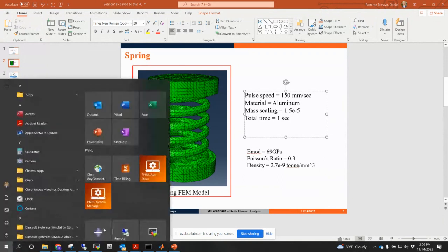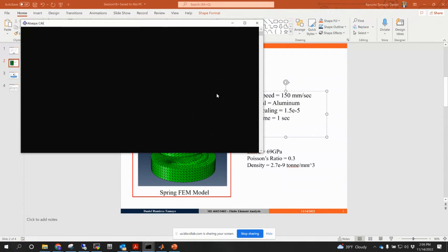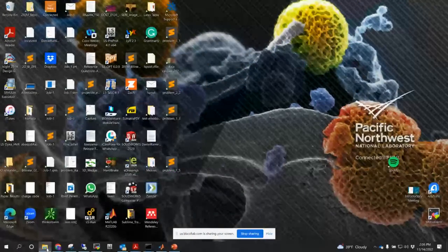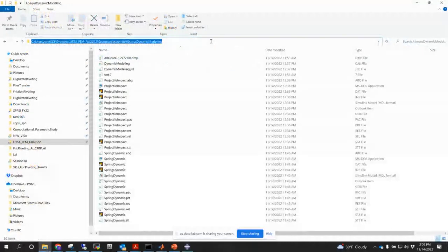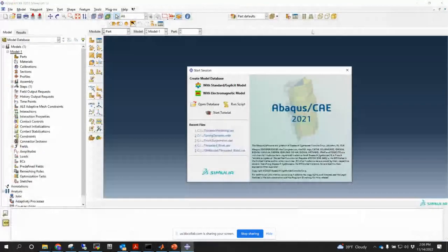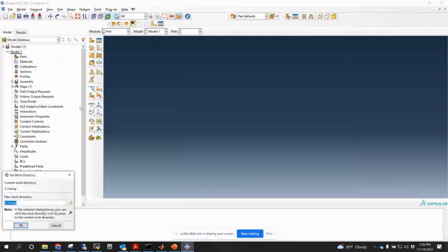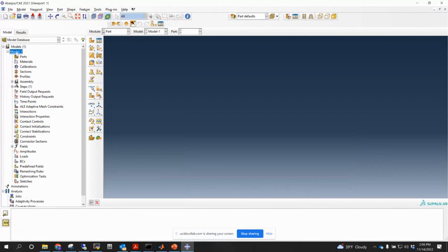So let's open Abaqus. And I'm gonna work on this working directory that I have in here, all right? So I'm gonna file, set my work directory, all right? And then I'm gonna rename this model, and I'm gonna call it spring.